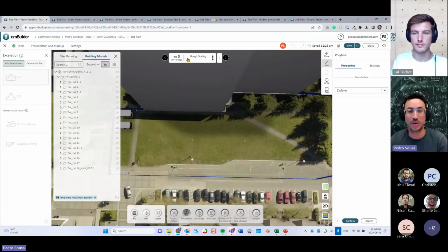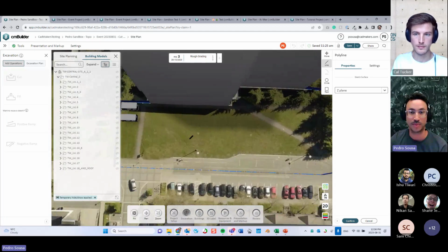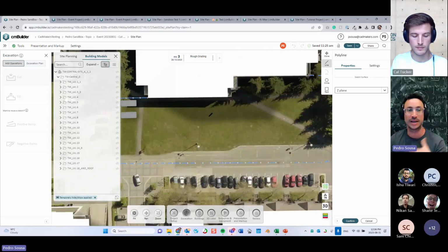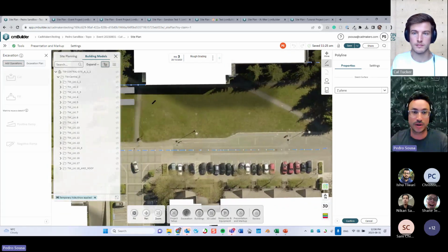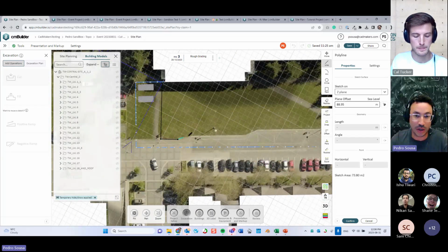And what we're going to do right now is the rough grading. So for the rough grading, we are not going to use the terrain per se. Oh, sorry, the model per se. I'm just going to use the shape of what we have over here. So I'm going to click and draw a shape just to clear up this terrain, following the curve.